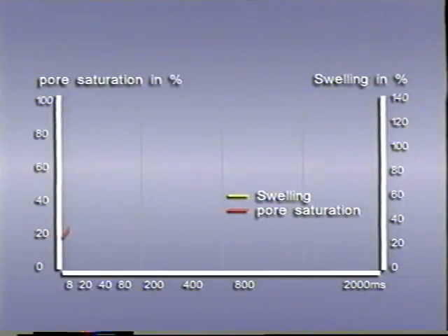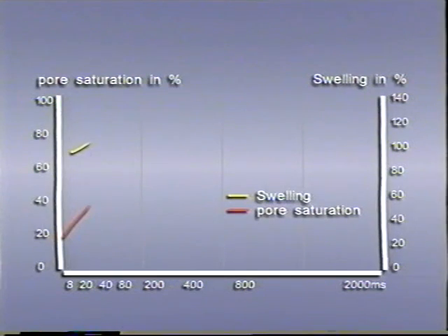The surface pores are filled during the wetting phase. After 10 to 80 milliseconds, the resin solution has also seeped into the accessible pores. Water absorption causes the fibres to swell. At the end of this phase, approximately half of the pores are filled, and the absorption process slows down dramatically.